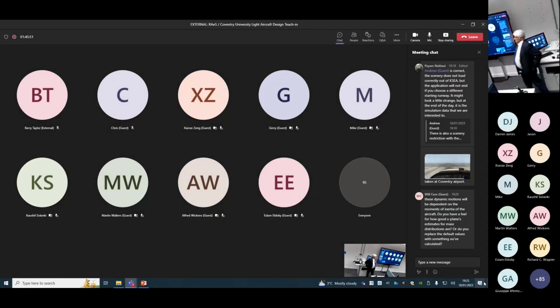Yes, in terms of the dynamic motion, the inertias, especially the IXX, IYY, and IZZ, are important, because when we look at the lateral motion, there is a concept called the concept of stability derivatives, and these derivatives are effectively formulated with either, in the longitudinal case, the IYY, in the lateral case, the IXX, and the mass as well.